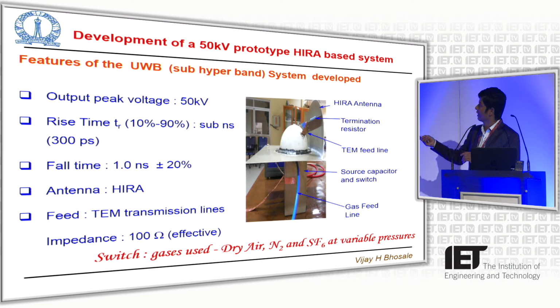This is the reflector type, which is completely similar to the half impulse radiating antenna, and this antenna is terminated by a resistive load. This is preliminary work developed by Vijay and his LRDE laboratory. The terminating resistors are mostly non-inductive type, because we are launching pulses on the reflector, and at that time there should not be any ringing effect. So we connect this sensor and we take care of this resistive termination load.